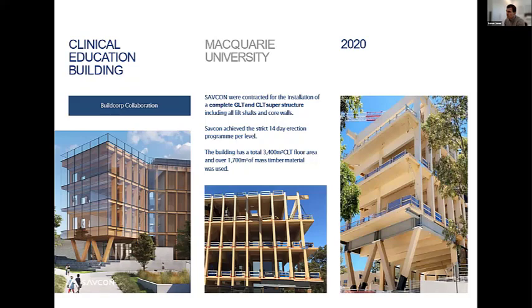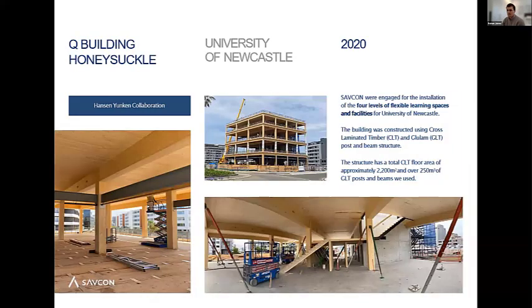And also the column to beam connections were a Sherpa connection. The lesson learnt from this project was that the Sherpa connection actually didn't come pre-installed on the element, onto the beams or the columns. So it was a good lesson learned for us and the builder to really understand the level of impact it has on the speed of us installing those Sherpa connections on site.